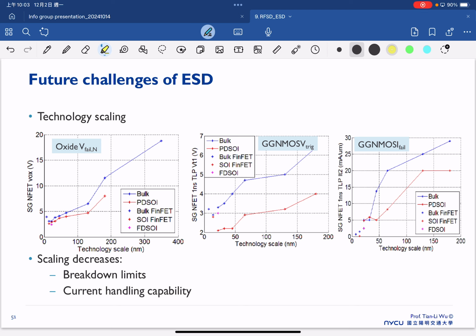Actually, we try to scale everything. That includes the contact hole area, the interconnection line width. That also includes the many different materials we passivate as intermetal dielectric, and stack. And even right now we have TSVs, through-silicon vias,